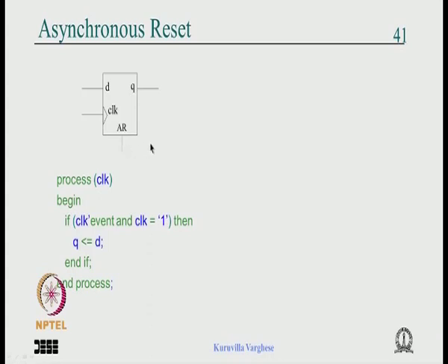We will briefly touch upon it, because if you don't reset properly there is no guarantee. First of all we don't know whether the Q will be 1 or 0, and sometimes strange things can happen, it can get stuck in between and all that. So you need a good reset, and the asynchronous reset.